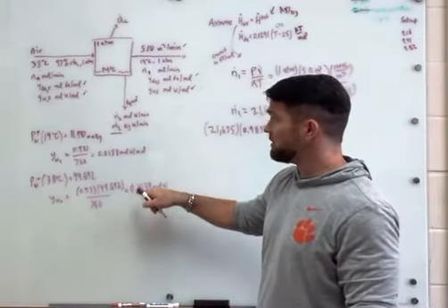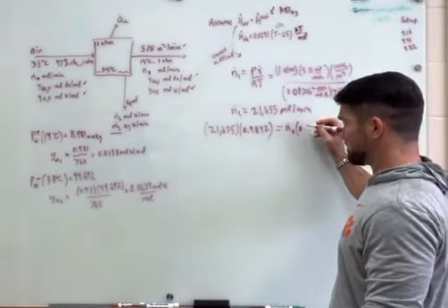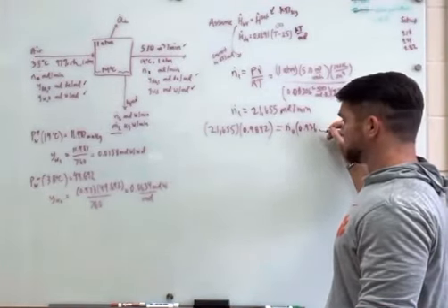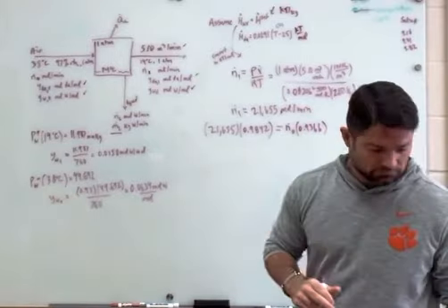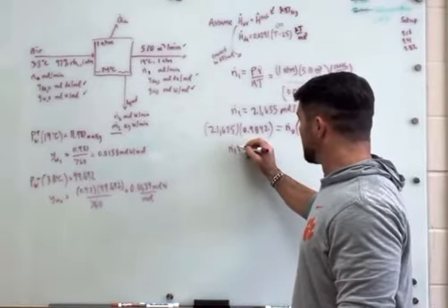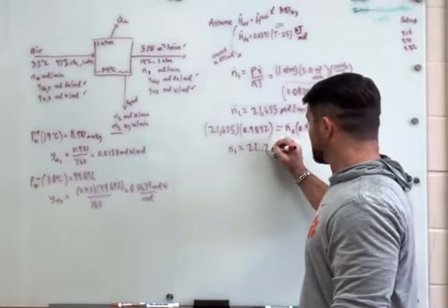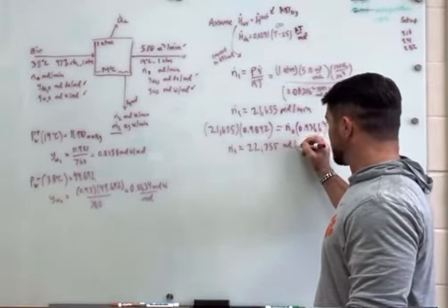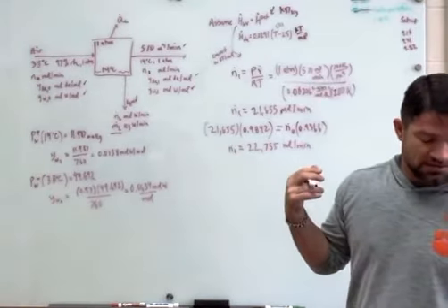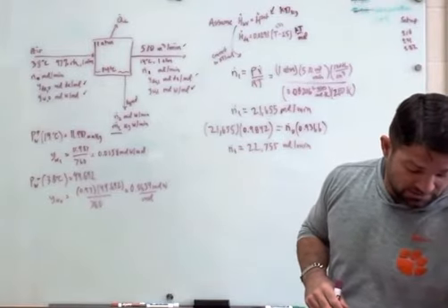The mole fraction of dry air in the stream entering is just 1 minus this value, so 0.9366. So then we can get this value N0, which is 22,755 moles per minute. I'm just carrying some extra numbers here. I have more significant figures than is needed, but I'm carrying them to keep my accuracy with the calculations.